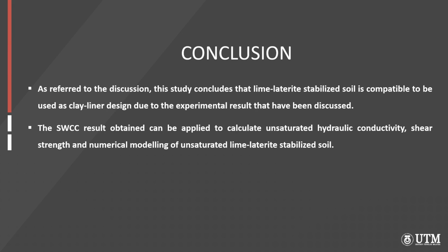As referred to the discussion before, this study concludes that Lime-Laterite stabilized soil is compatible to be used as a clay liner design due to the experimental results that have been discussed. The SWCC result obtained can be applied to calculate unsaturated hydraulic conductivity, shear strength, and numerical modeling of unsaturated Lime-Laterite stabilized soil.